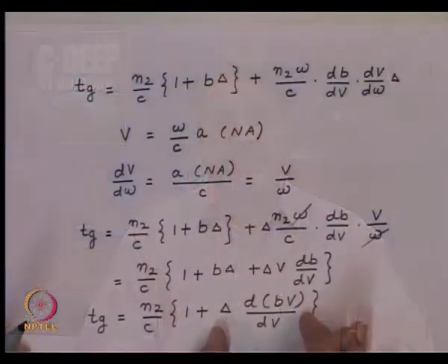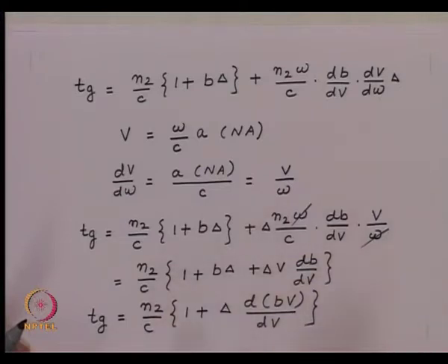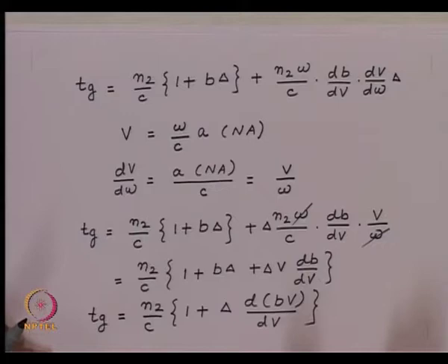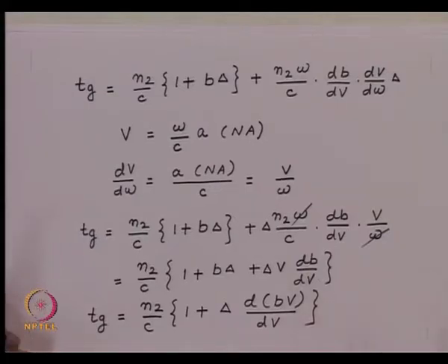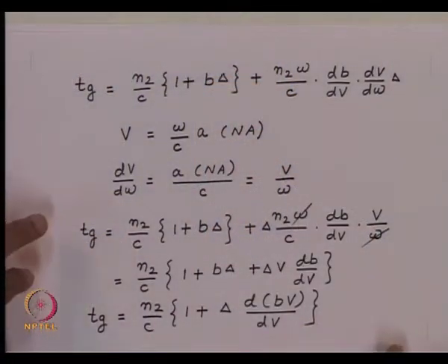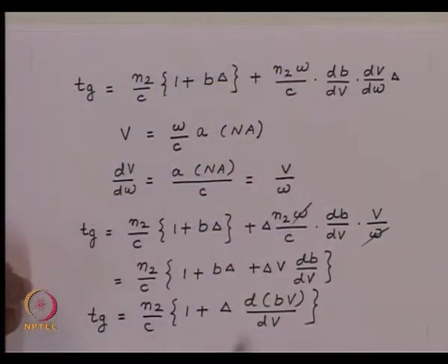This is the quantity essentially which is telling you the differential velocities. So this is the term which essentially will give you something which we are interested in, that is the dispersion. So every signal is going to undergo a delay which is constant, which is not a function of wavelength or frequency. This is the term which is going to give you a differential delay, and that's what will give you dispersion.